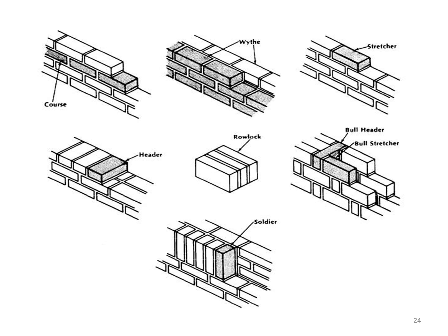Now here we don't show the other type, but if the flat face, the longer face of the brick was standing up and placed to the outside, that's called a sailor type, so in opposition to the soldier. And the way to think of that is they're wider at the base, just like sailors when they stand on the deck of a ship. They have their legs spread. They don't stand with their legs together, heel to heel. They have their heels spread out because the ship yaws and rolls, and that's just a sailor's position. So that's the difference of the positioning of a soldier and a sailor row.